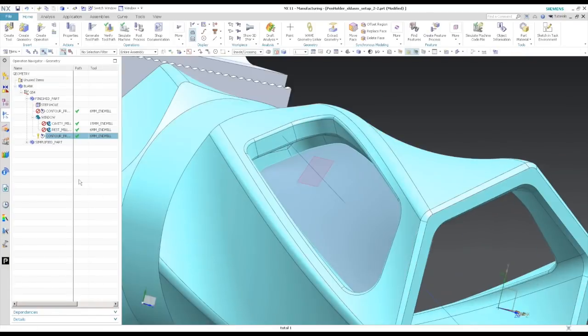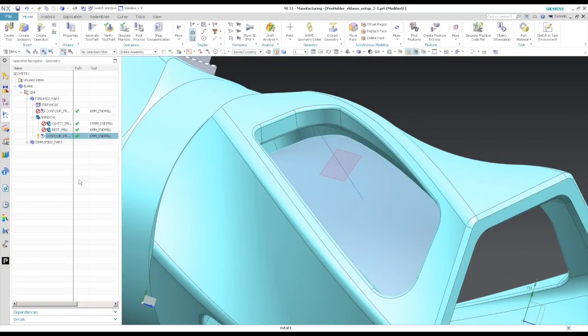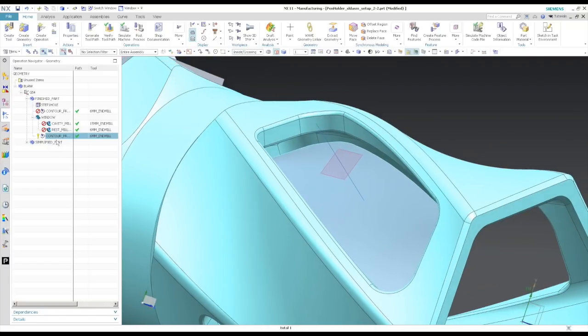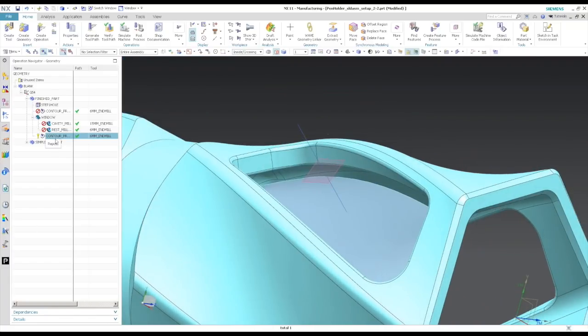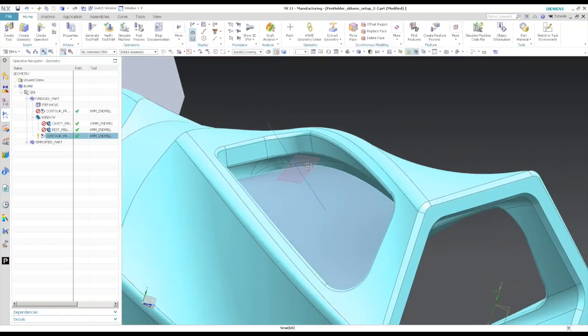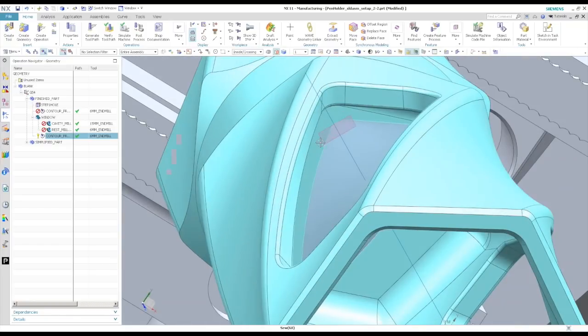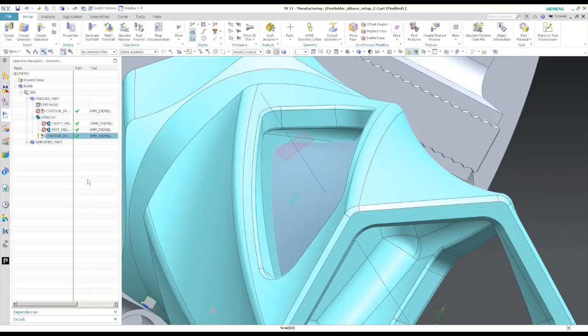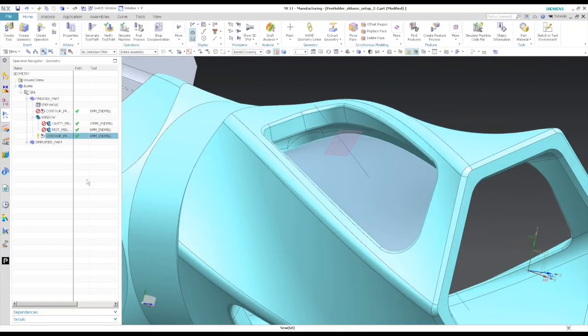The programming time was shorter, but we had to do a step down or a stitching type toolpath. If the part had been modeled in NX with good data, we could have put toolpath on it extremely quickly because of the good UV lines, and created a toolpath that was 20x faster, because it could have used the side of the cutter instead of having to step down at multiple tool axes or fixed tool axes, 3+2 machining.